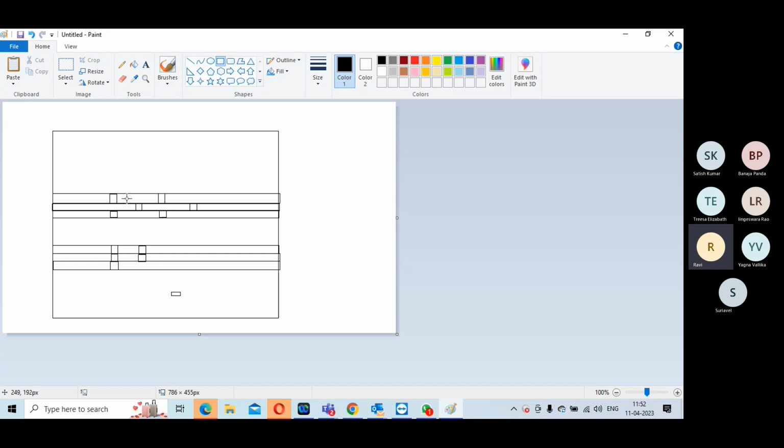Now look at this scenario, because you will eliminate almost 50% of the tap cells. Here, at the top, I am placing a cell over here, say 50 micron, but this distance is 150 micron. In this case, this has to be 100. Here I can space it in a single row at 200 micron, because in between I have another one, so if I place something over here, the cross distance becomes 100 micron for me. It is okay. You understood, right? This is the reason why it is placed in this particular fashion.